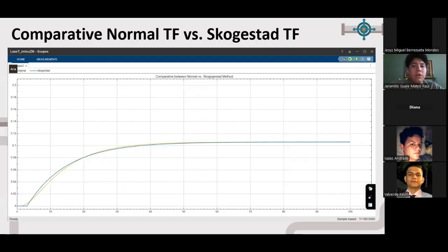Next. This figure shows the Simulink scope of the original second-order plant compared with the simplified FOPDT plant. When we compare both graphs, we can see that both of them show very similar behavior because rise times are set and settling times are almost the same.